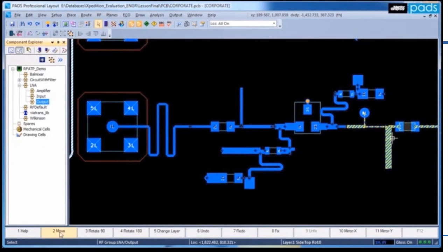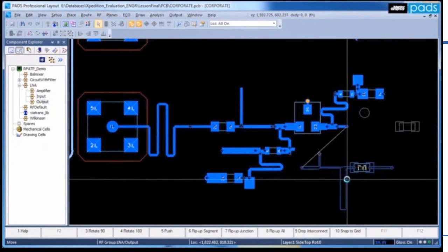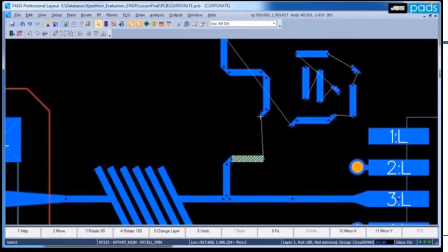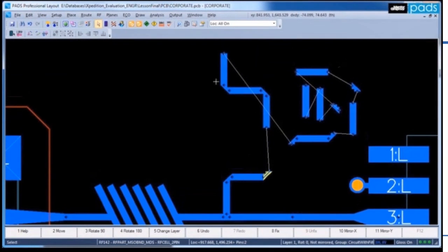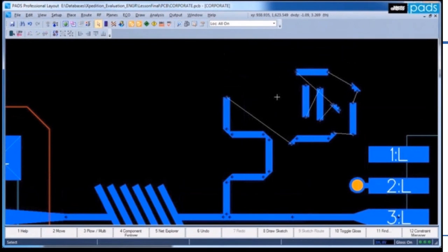Moving and connecting shapes is fast and easy, as the cursor will always attach to the pin. Simply drag it close to where the shapes are and release it, and it will snap into place. A subset can be moved and connected to other shapes as a unit, and by stepping through the non-connected pins, you have full control over which end to connect. To automatically arrange a subset of the circuitry, simply select the shapes you want to arrange and define the seed on the fly.